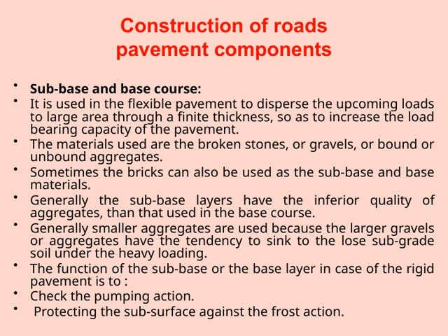It's important to note that the subbase layer generally consists of lower quality aggregates compared to the base course. This is because the subbase doesn't need to withstand as much load, and using inferior materials helps keep costs down without compromising the overall performance.